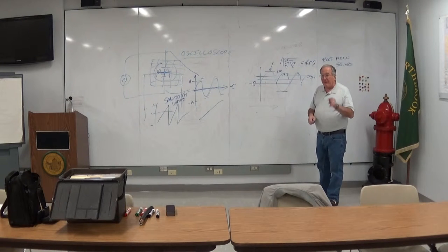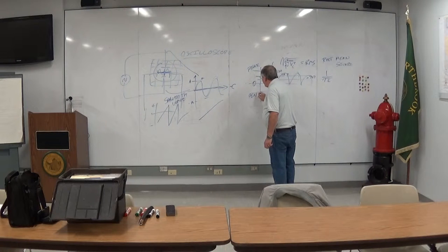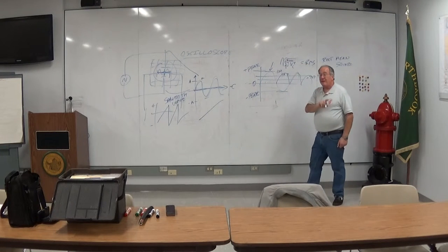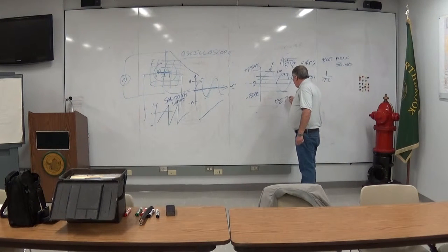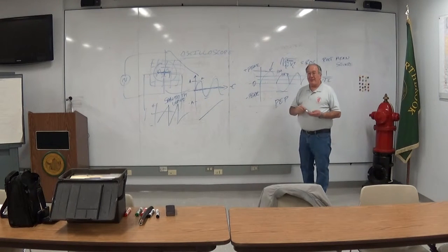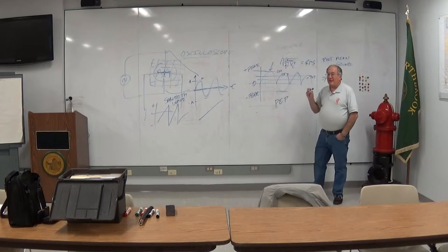And by the way, be very careful here. There's a difference between 0 to peak and peak to peak, which is the negative and the positive peak values, or what they sometimes refer to when you look at, for instance, single sideband power measurements. They talk about PEP, which is peak envelope power. That means from the extremes. And that will be double the 0 to peak value. So you have to pay attention to the way the question reads.